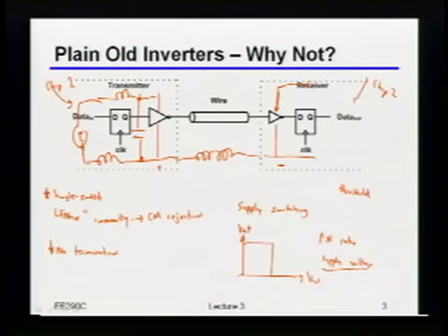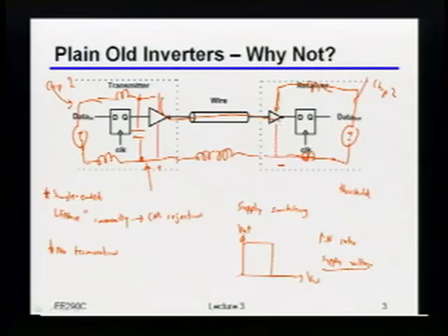But now, does me having a bypass cap right here help me at all, given the fact that some current has to flow out through that transmission line, and then come back, guess what? Through that ground loop? Not so much, right? Because the bypass cap just makes sure that this relative to that is fixed. It says absolutely nothing about this ground over here being the same as that ground over there.